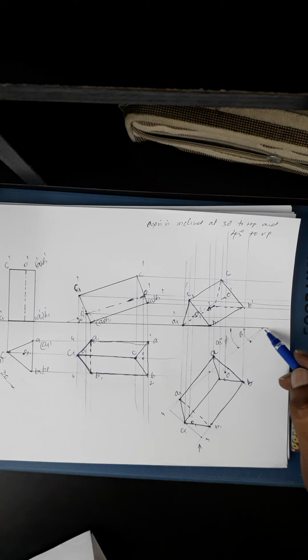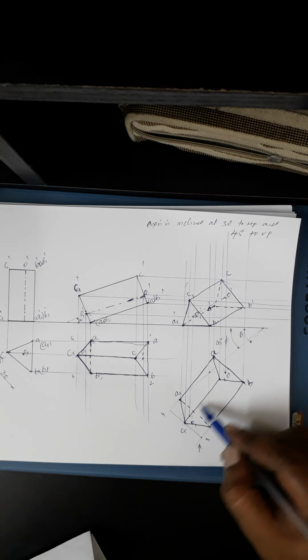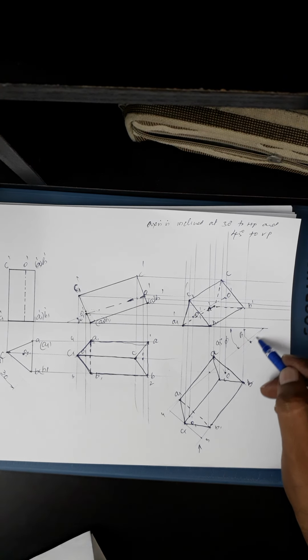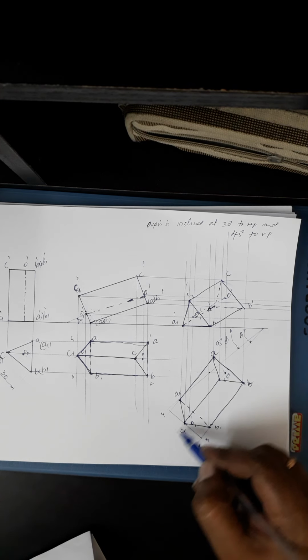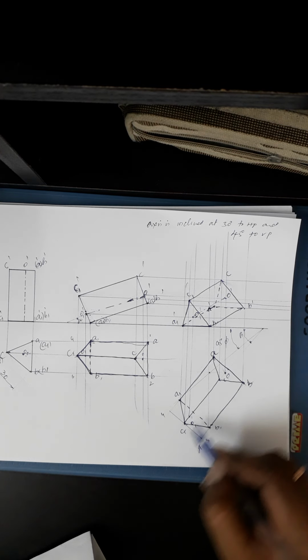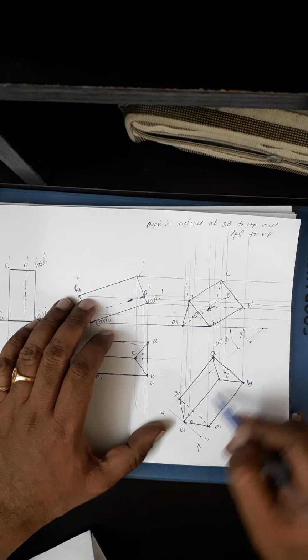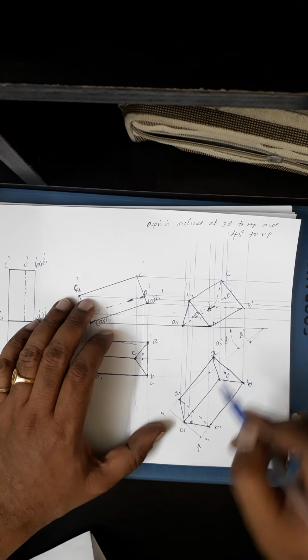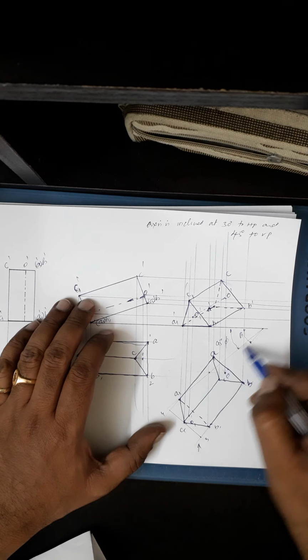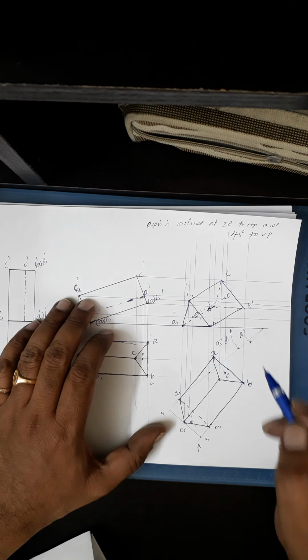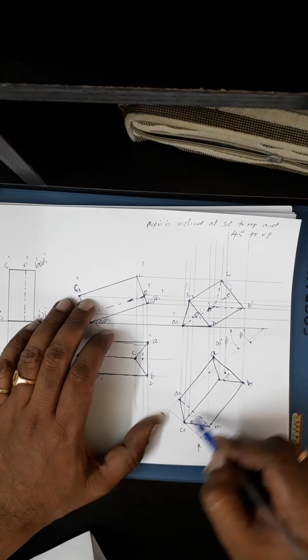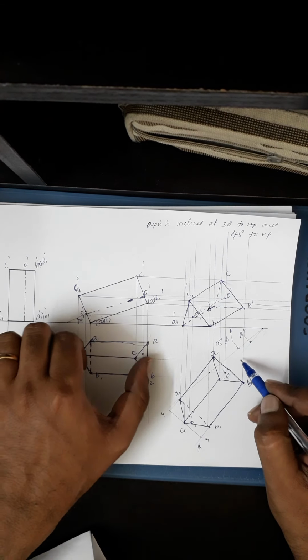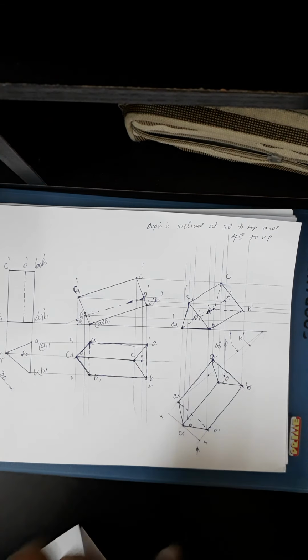Now you forget about this line. This is now the inclination. At beta you have to redraw this view. So go for drawing that line. Extend that line. This is the axis line where you have to incline with this beta, which is more than 45 degrees, not at this. Now you forget about the line you have drawn; let it be very thin when you draw it after finding this beta angle. So this is my axis line where you have to redraw this so that this axis coincides here.